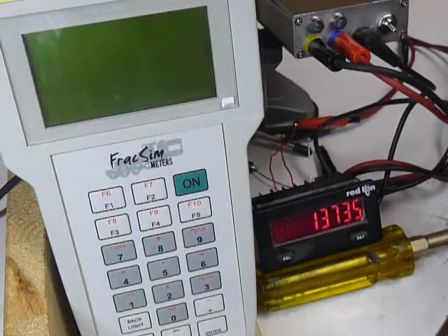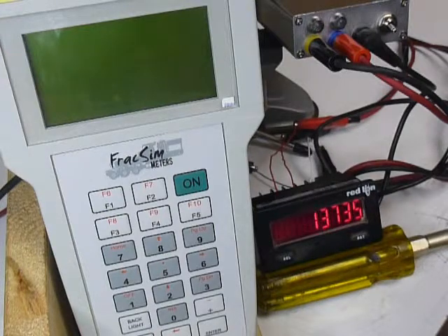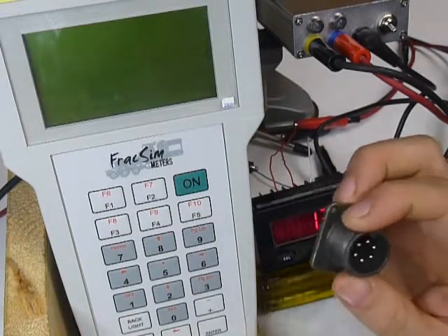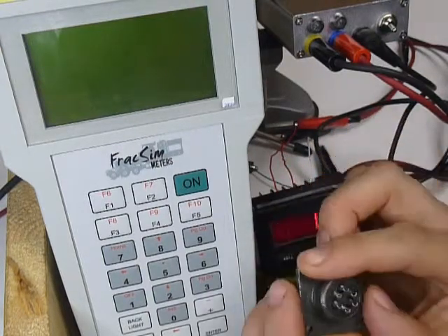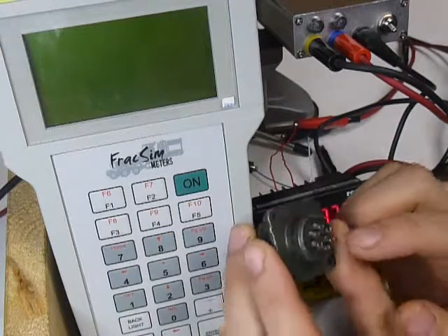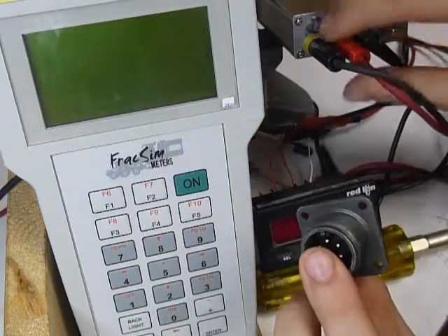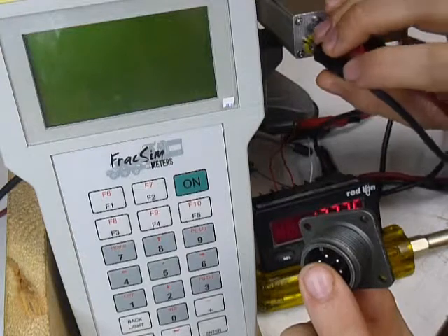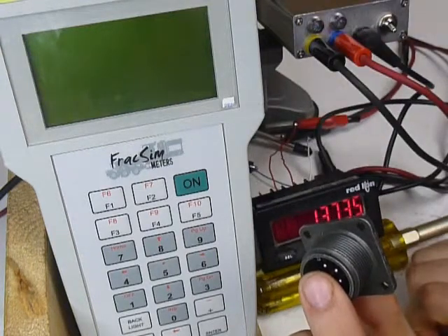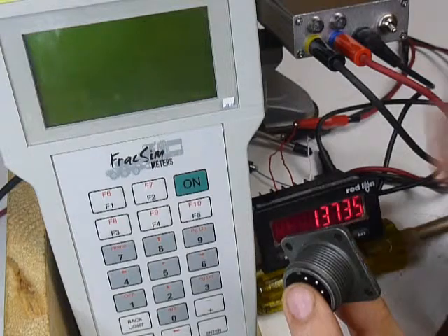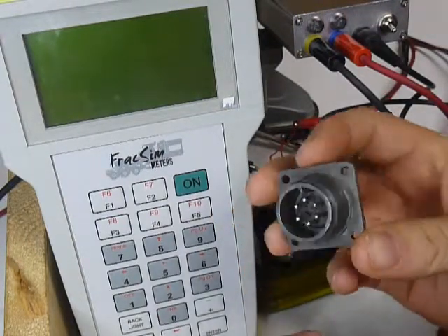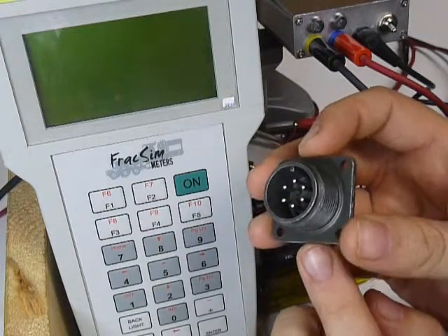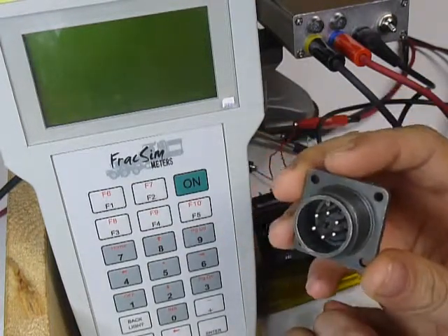One more thing I might recommend, if you were going to be doing a lot of simulating on a certain type of encoder, what I would actually do is round up an old broken encoder, take the connector off, and solder a couple wires onto the back of it, so you could go directly from this connector to a couple banana jacks like this, and that way interfacing in the field or in the shop, wherever, you can just quickly plug in your couple leads and screw this or whatever type connector end you have directly into the unit to make the whole system a lot more efficient.